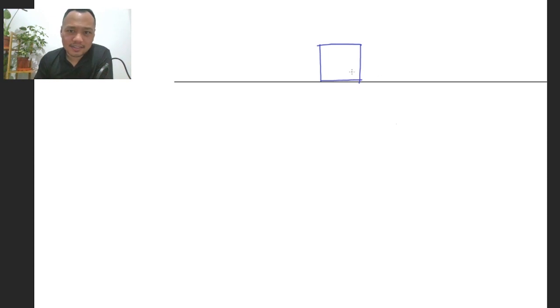Now you cannot have one of the sides of your floor plan directly on top of the picture plane line. Okay, so what we do is we typically rotate it clockwise 30 degrees. Okay, and then after that we take the corner that's closest to the lowest corner, and we rest it right on top of the picture plane.